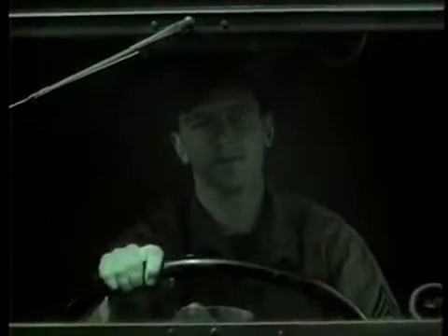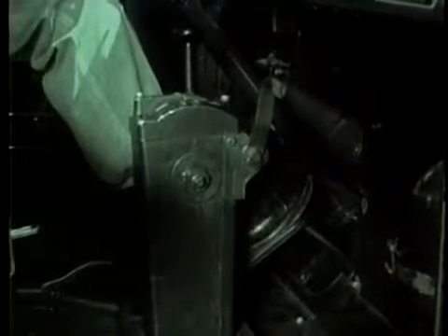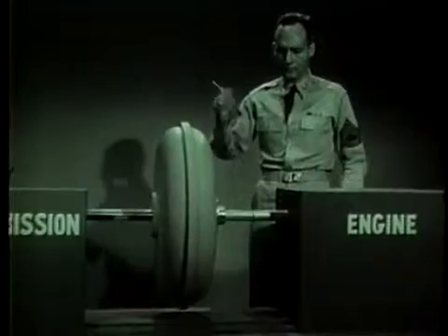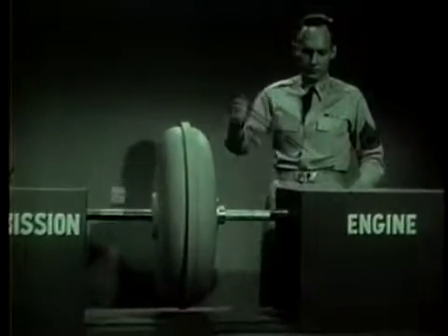When the driver releases pressure on the accelerator, the momentum of the vehicle tends to keep it moving at the same speed. This causes the pump to slow down, but not the turbine. In other words, the turbine overruns the pump, and because it's built almost exactly like the pump, the turbine will transmit energy back to the pump. In effect, the turbine tries to drive it. Engine compression, however, resists this attempt of the turbine to drive the pump and results in the vehicle slowing down, such as would happen with a conventional clutch.